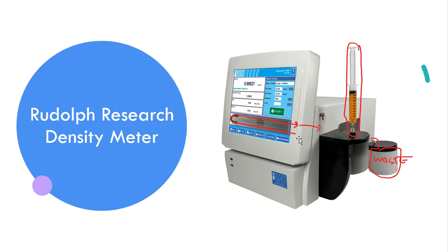So you'll insert the sample, you'll overfill the U-tube, and then there is a temperature setting that you will put into the computer software on the instrument, and you'll key that in at 25 or 35 or 40 or 20, whatever you need, and then it will heat up to where it needs, and then it will begin to make the measurements at that temperature setting.